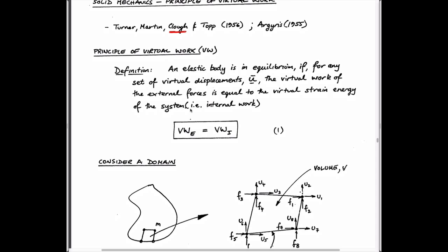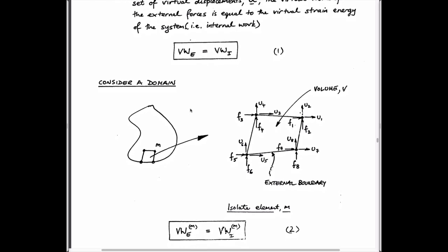That work has to be present inside the system, and so if you measure the stresses that those forces apply to the system and the strains that now are made by that small displacement that you apply, the product of the internal strains that develop and the applied stress has to be equal to the displacement that you apply on the outside multiplied by the force that was already applied on that system. And so if you can quantify both of those two components, you can put those together to be able to explain the behavior of the system. And so that's what we're going to attempt to do.